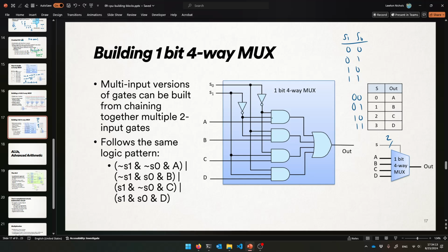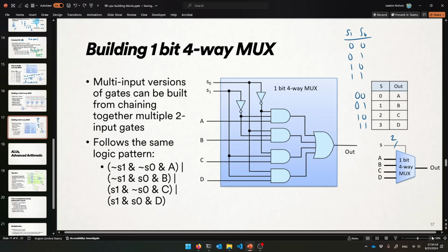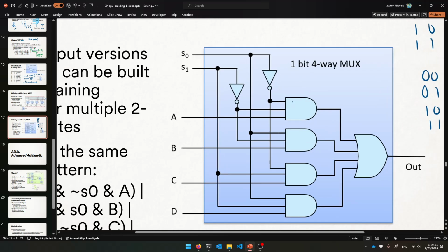We're negating some things. This is an AND gate that takes 3 things and ANDs them all together in some order. You can imagine that this is built of 2 smaller normal AND gates, right? You AND these together first maybe, and then take this one, AND it with the result. That's kind of how that might work. And same for this like 4-bit OR gate. It's like ORing together these 2 things maybe, and then ORing together these 2 things. Sorry, I need more ORs, don't I? So first we have to OR these guys, then these guys, and then one last one, don't we? So that's kind of how it works. It's just ORing a bunch of things together, just like this was ANDing a bunch of things together.